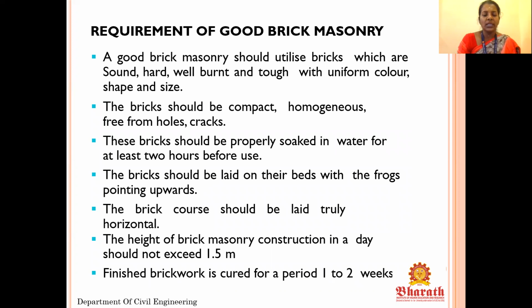These bricks should be properly soaked in water for at least 2 hours before use. So before constructing the wall also, the bricks should be soaked in water. After the laying of bricks, when everything is over, water should be poured on the wall for proper curing. The bricks should be laid on their beds with the frogs pointing upwards. The brick courses should be laid truly horizontal.